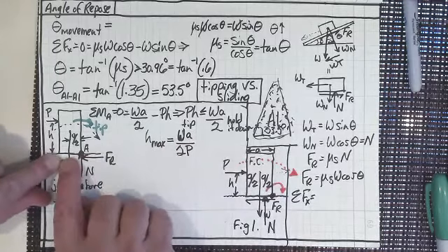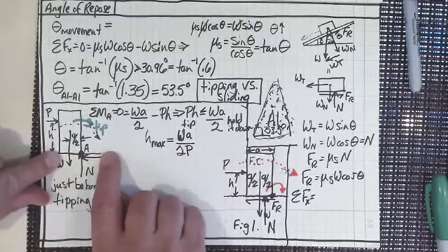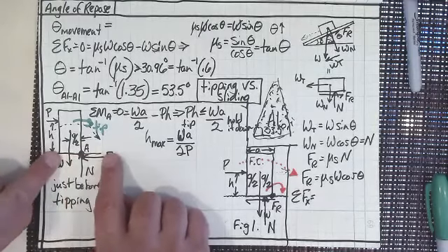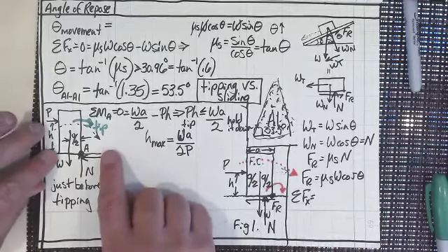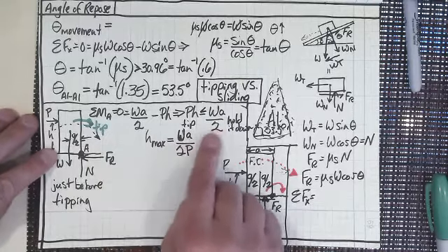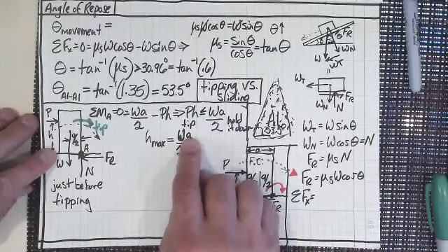So in other words, if I had a much wider desk or a table, if I increased A, then we wouldn't really have slipping and tipping. When have you ever pushed a table across the floor and had it flip over? Hardly ever, right? And of course, that's because A is so large.